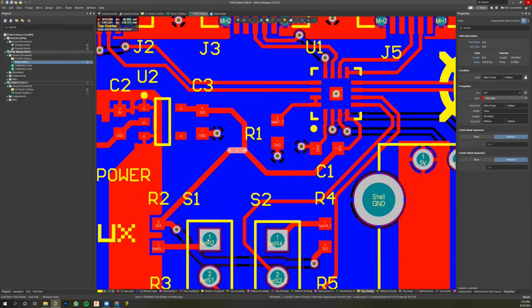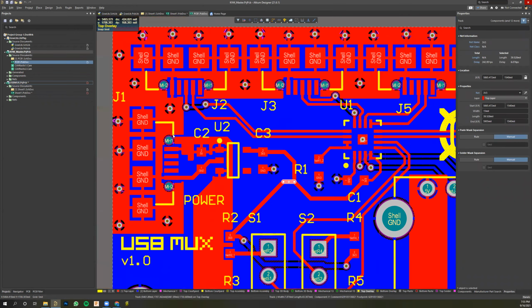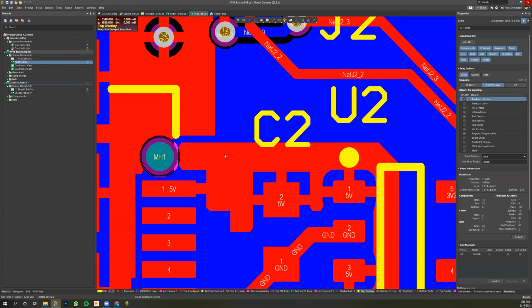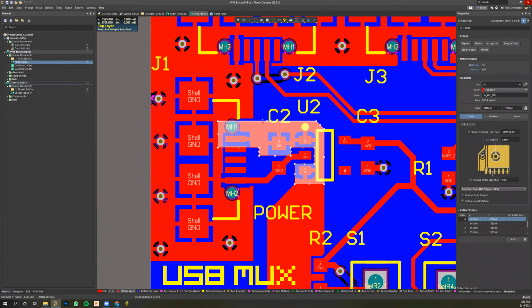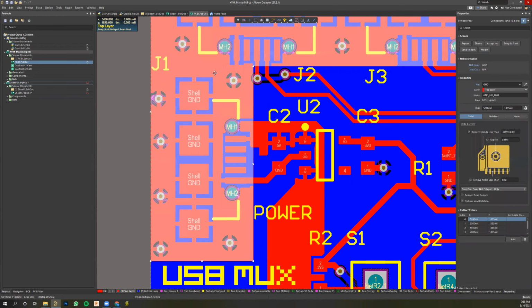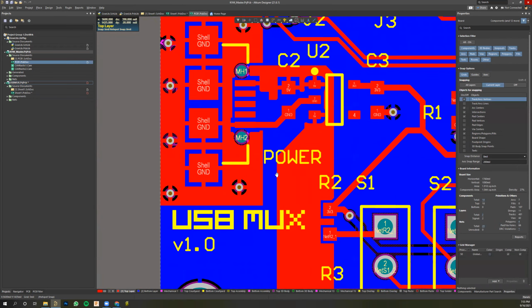And because we set those clearance constraints earlier, Altium won't let two polygons interfere with each other. In fact, you can see two different polygons. If I can get it to click. There it is. Okay. So there's one, and you can see it extends all the way into here, technically. And then there's another one, and you can see Altium did not allow them to interfere with each other because we set up those clearance constraints earlier.